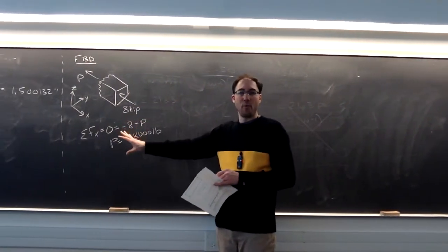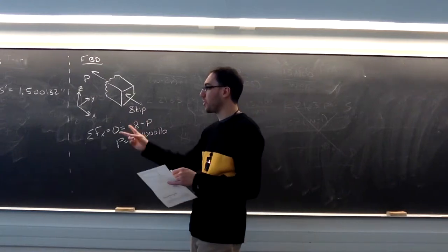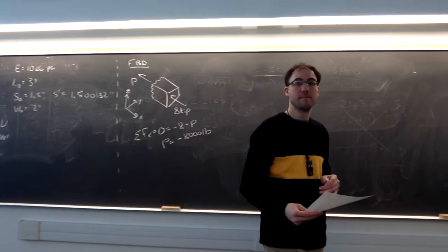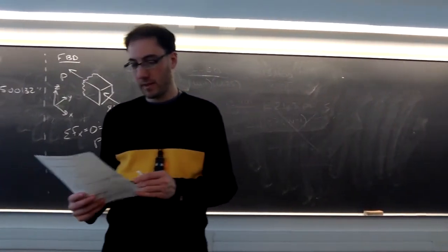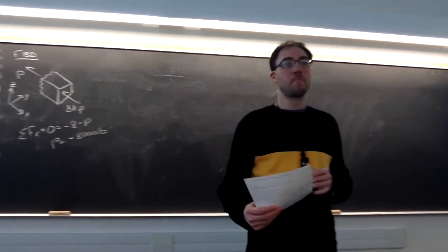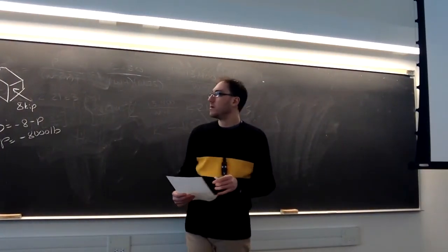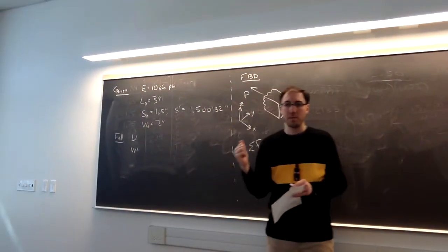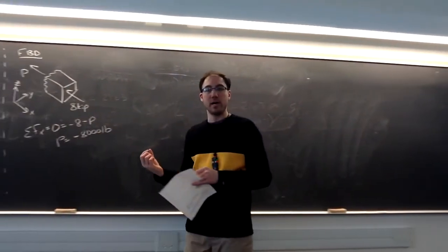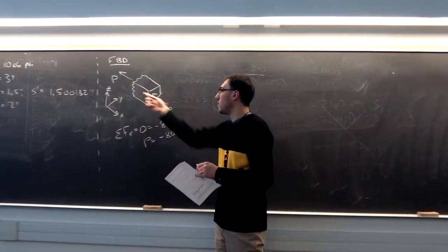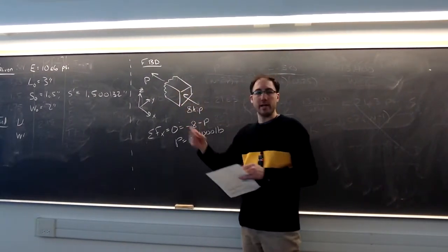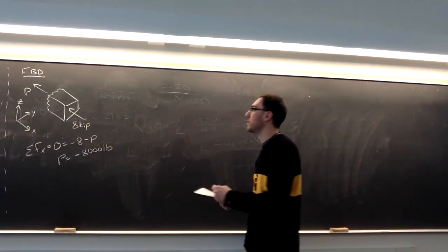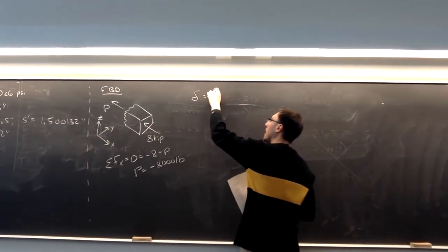All right, with that out of the way, where can we start to solve for the 2 things we need, the new side length W and the Poisson ratio? So again, this is some of the information we know. We now know the internal force P. We can find delta, the change in length along the L direction, because along the L direction is where we have this internal load P. So this is being caused by the applied load. So the delta we can say is PL over EA.